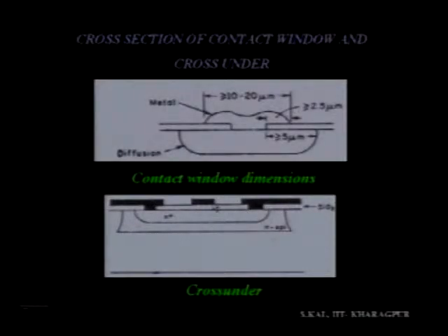So if this metal line passes from this and this is perpendicular to that, it will interconnect, a short circuit will be made, isn't it? So in order to avoid that, what we normally do, in this isolated N region, you diffuse an N plus region. N plus is highly doped, and a highly doped region will give you a very low resistance. Almost metal-like conductivity can be obtained by a very high doping level.